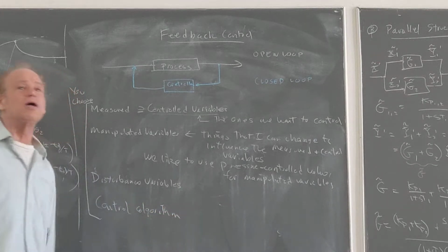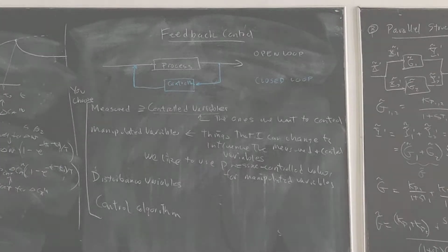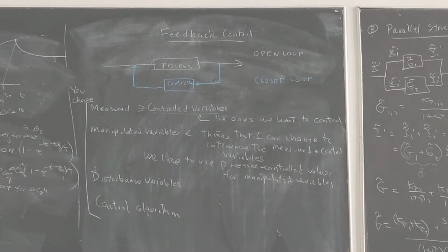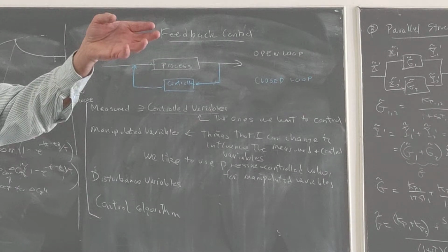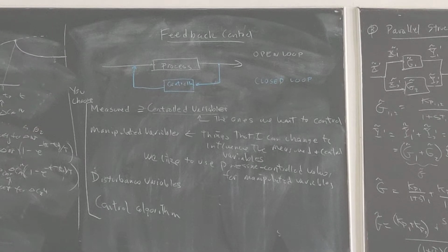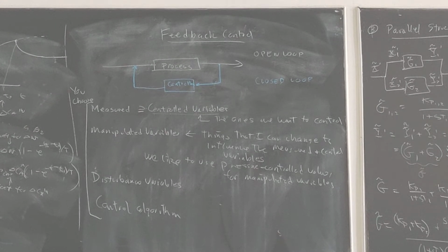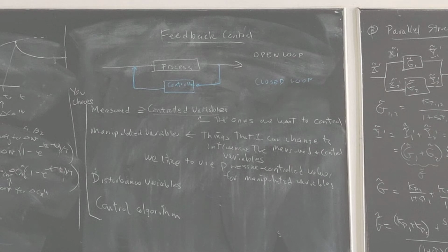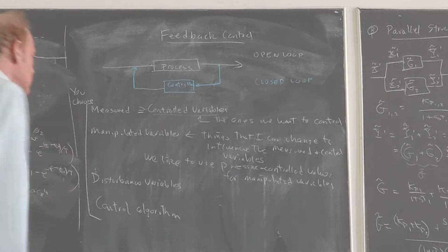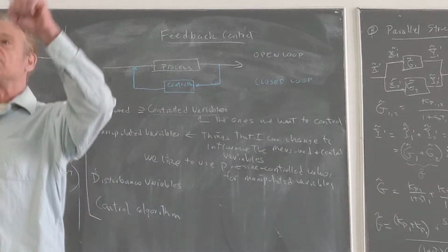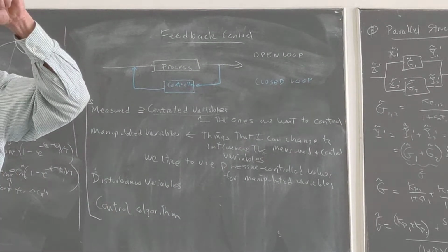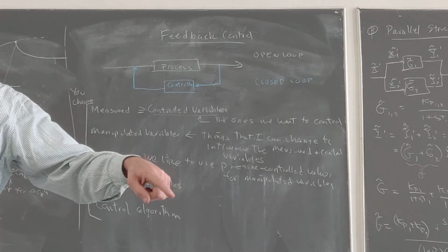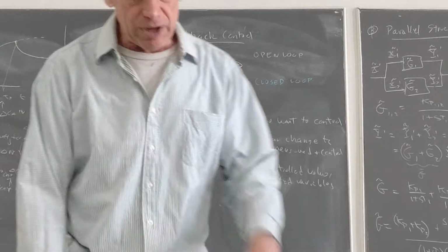That is, what you want is an algorithm that automatically does the control. You don't want someone sitting there looking at 200 different screens, and when something changes, having to figure out which valve to turn or which pneumatic button to press. Most of the time, you want the reactions to be automatic, and only when something goes terribly wrong should the operator have to do something. But you shouldn't have to do the routine things. So the control algorithm says, when this variable goes up, then open this valve. When that variable goes down, close this valve, etc. So you want that to all be automatic.